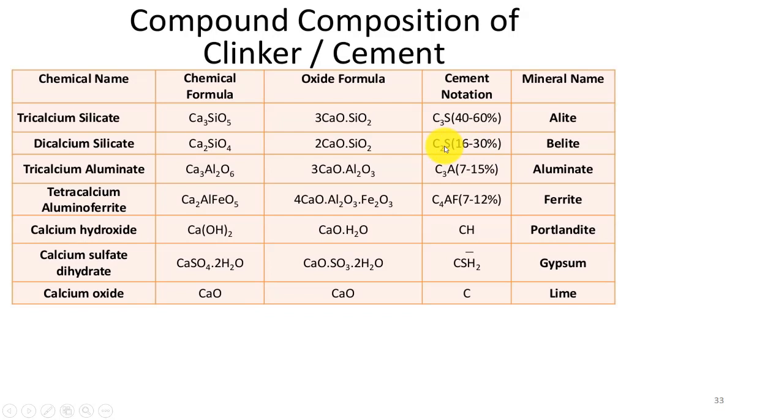It contributes toward the delayed hardening of a cement. Thirdly, you have tricalcium aluminate, which is for the early and final setting. Basically, these two products, tricalcium aluminate and tetracalcium aluminoferrite, are used to have an initial and final set.